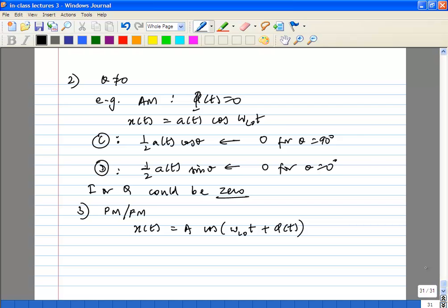Synchronization will need to be done, whatever RF signal you are receiving. It is difficult, because what you are receiving is only the RF signal. You don't know what phase information is there until you down convert it, and to down convert, you need something which is synchronized, which is impossible. You're going around in circles. So you can never synchronize the two.